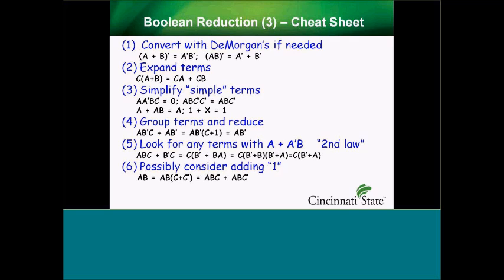The problem is that if you have something like this NOR gate that you have here, if it's got a term outside it, you can't bring it through until this thing is converted. Students will try to do it. They'll try to bring a C in here or D or whatever it is and expand it out, but it won't work. So the first thing they have to do is expand these things out. These NORs and these NANDs, they've got to expand them out. That's the first thing, because once you do that, then you can write everything out in terms of SOP form.